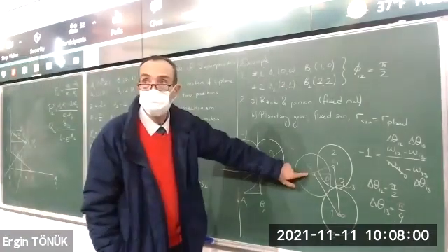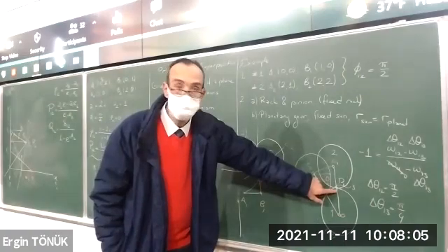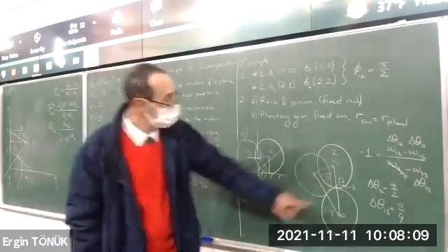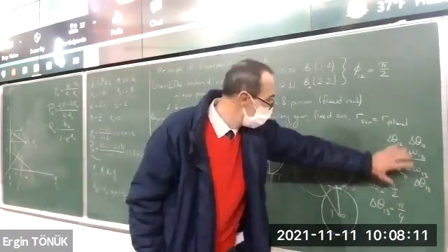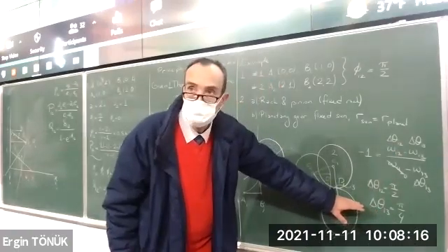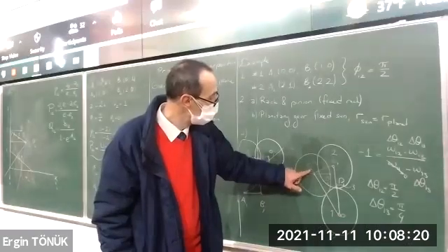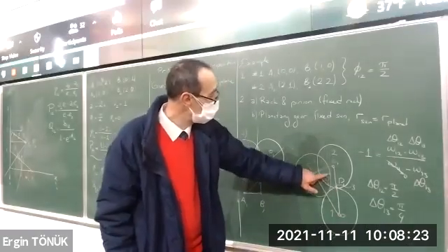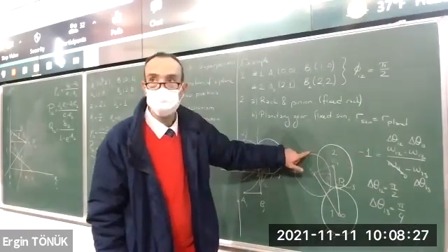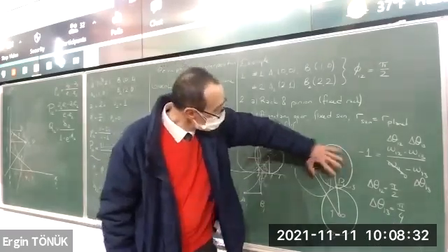This point is, yeah, now it should rotate by 90 degrees. Okay, this is what I have. The gear relation tells me that the arm should rotate 45 degrees. So I draw this. D in contact here will come to here. Or if you select, I don't know, E here, it will come up. If you choose F here, it will come down. Because this is rotating 90 degrees.